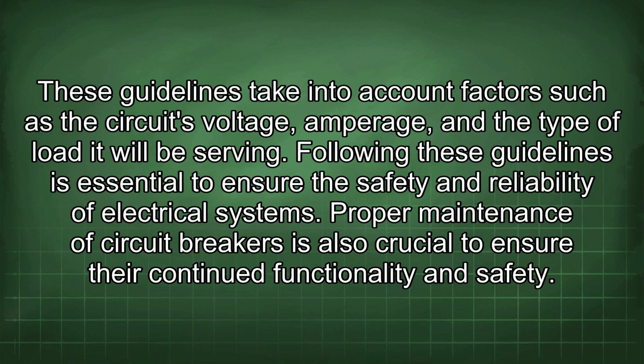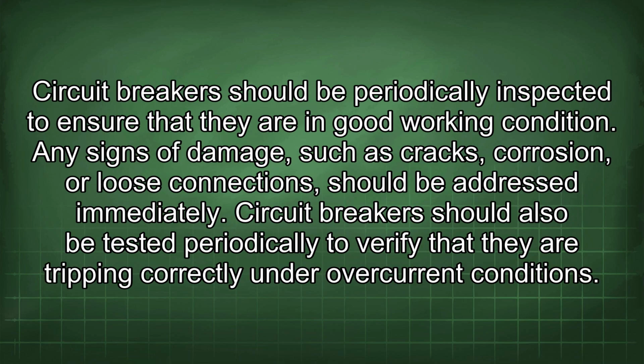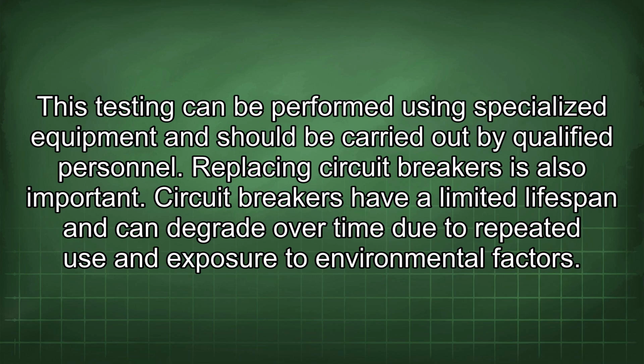Proper maintenance of circuit breakers is also crucial to ensure their continued functionality and safety. Circuit breakers should be periodically inspected to ensure that they are in good working condition. Any signs of damage, such as cracks, corrosion, or loose connections, should be addressed immediately. Circuit breakers should also be tested periodically to verify that they are tripping correctly under overcurrent conditions. This testing can be performed using specialized equipment and should be carried out by qualified personnel.